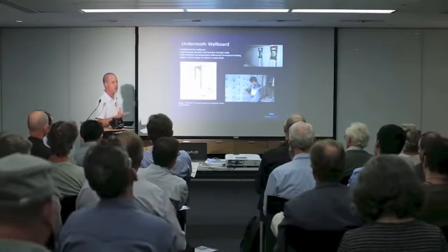So the good thing about phase change is if you've got a badly designed house, you still get a great benefit. In Melbourne, we have about 200 days per year where we don't have to heat and cool a house. I imagine it's probably fairly similar in Sydney. With phase change material, at my house, it's jumped up to about 300 days per year where I don't have to heat and cool actively.